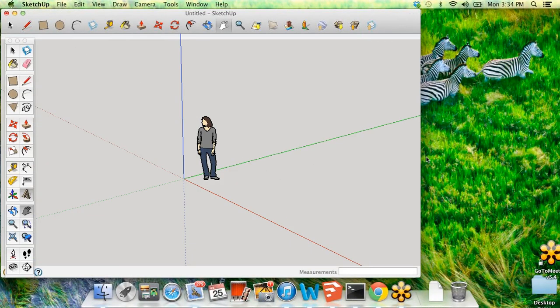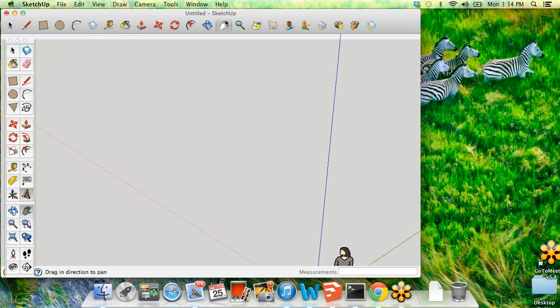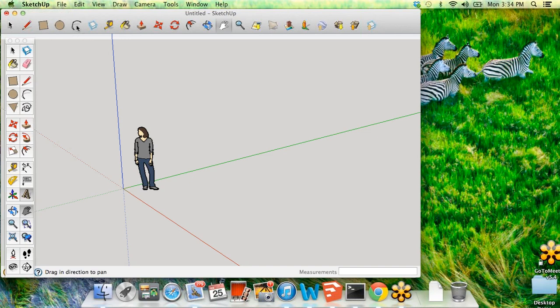Everybody can pull up SketchUp. So we have this arc. If you guys could just please be working along with me here. You have your start, your finish, and then you can pull it and push it into a bulge. Once you get it started, before you click, you can simply type without clicking on anything else. You can simply type 1000, and that will specify how far up that center line was to fix the bulge.